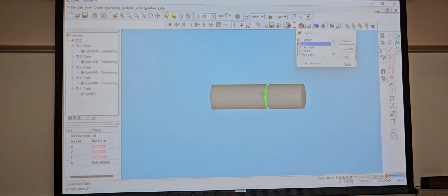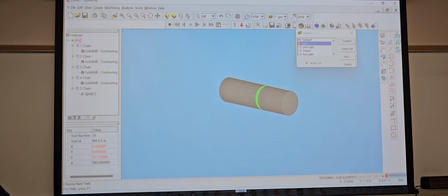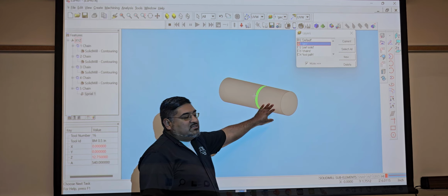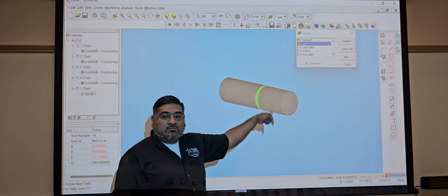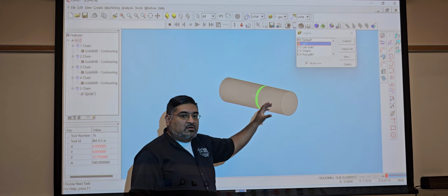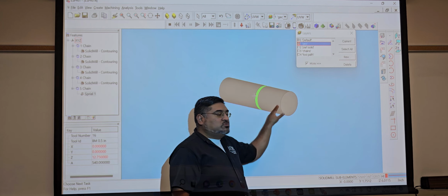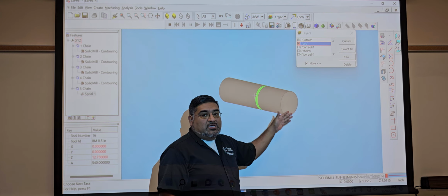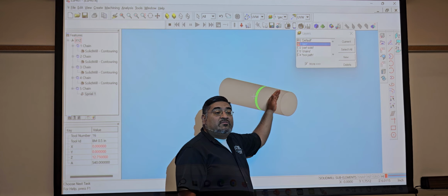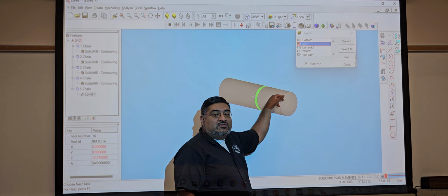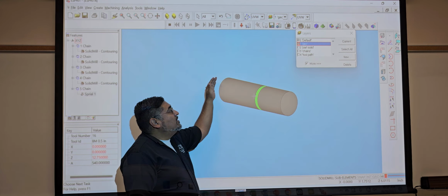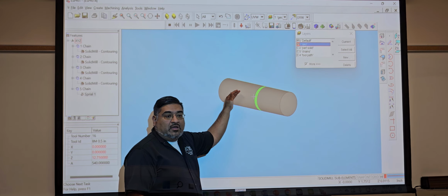So, finished what I was doing there. For the chamfers, you could do it both ways. Like if I just have my solid and I didn't actually draw the slots, it's gonna create a whole circle around it, right? So that's cool. I could just click on that, make those chains, and just use -50 on the walls. Create the chamfer tool, and it would do that one, right? But obviously back here, that one's gonna be +50, correct?